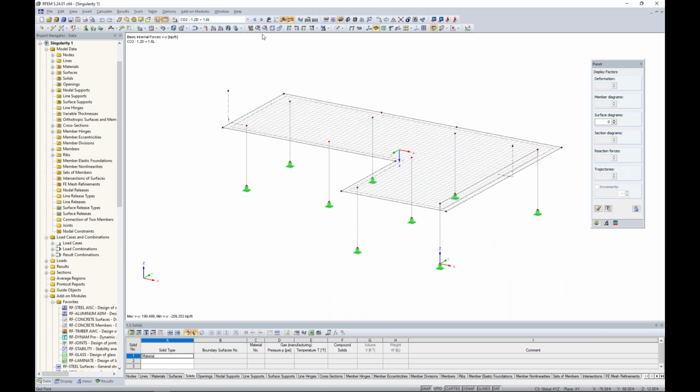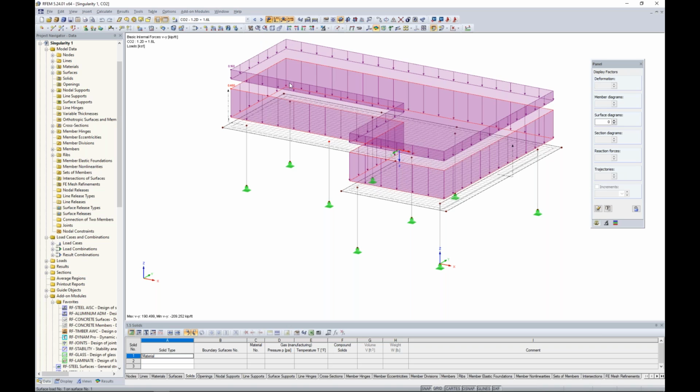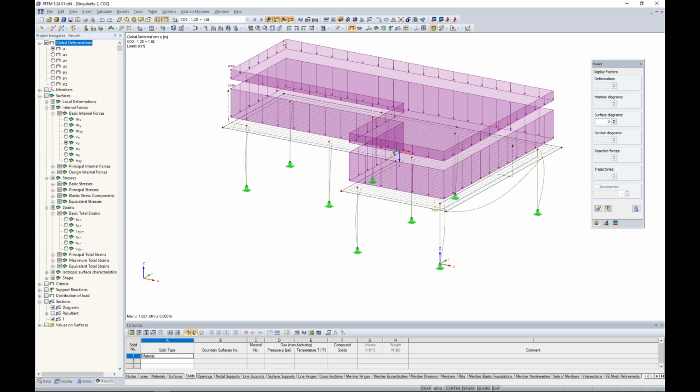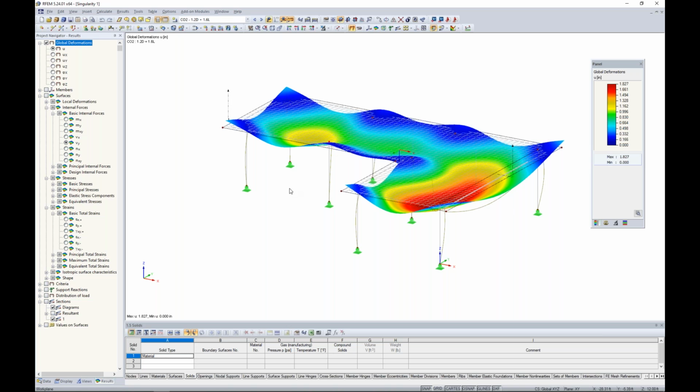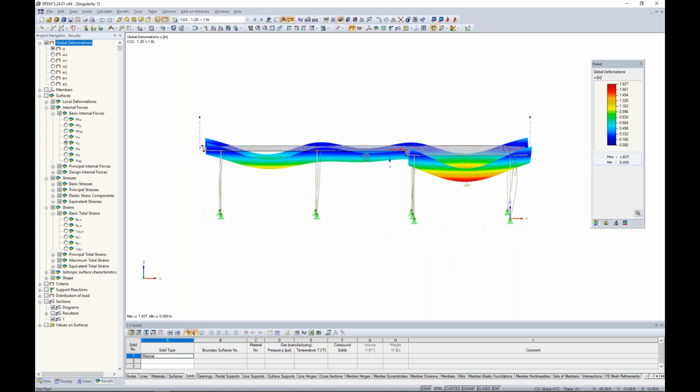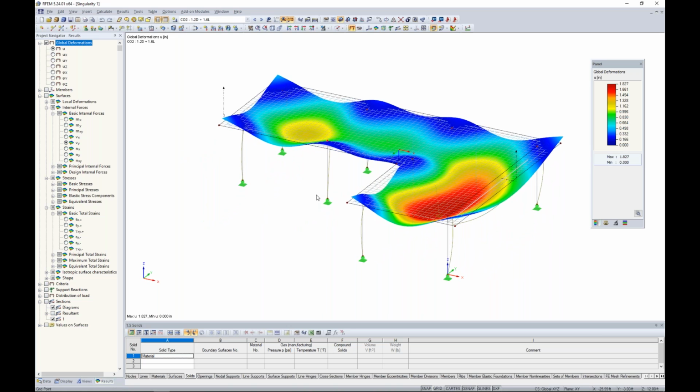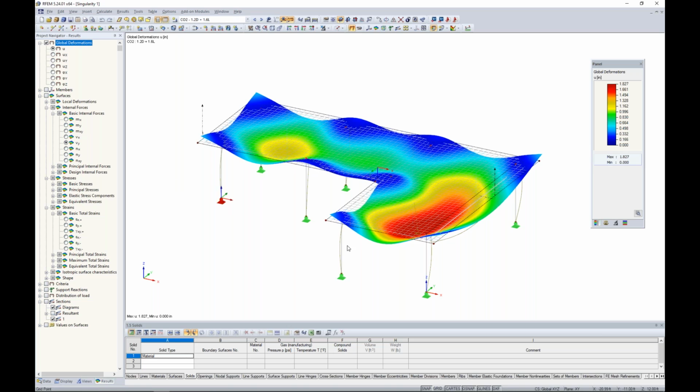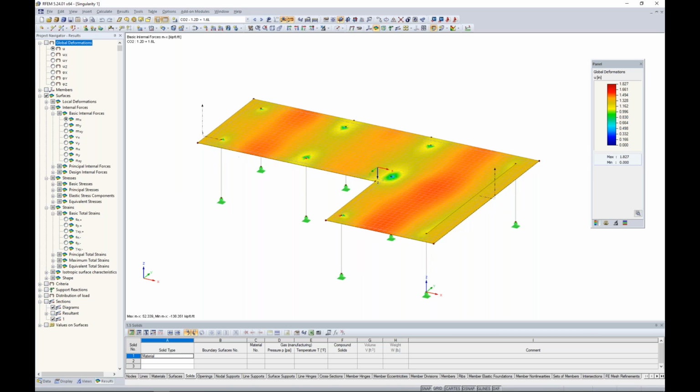So you can see for this example, what I've done is I've applied a couple gravity loads here for dead load and live load. And if we run the analysis, which I've already done in this case, and we take a look at our results, we'll turn on our ISO bands, turn off our loads. Well, okay, the initial deflection, nothing too strange here. But let's take a look at the internal forces for our slab element. And so we'll turn this on and we'll take a look at MX. Well, initially looking, MX looks okay.